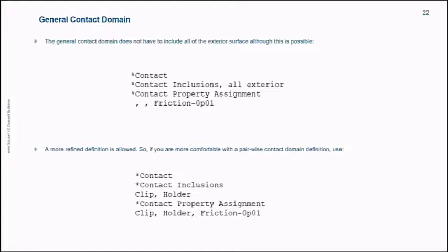Okay, so I was doing my disk through the ring problem with the contact pair, and I had issues with the edge sliding, so I quickly just changed star contact pair to these commands here with a text editor. It took a few minutes to do that, and then I was able to run that with general contact instead of the contact pair.